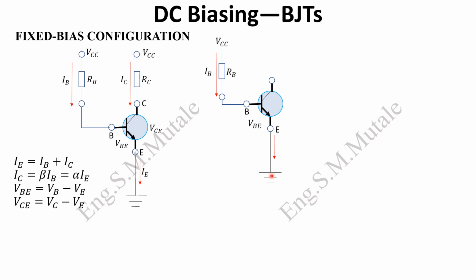So this voltage, as it comes from the point of excitation, you are going to have a voltage drop across the base. You're going to have a voltage drop here, which we are calling VBE, and then it goes to the ground. The one thing you need to note is that VBE is 0.7 for all transistors. They may or may not give you this, but whenever you see VBE, just know it's a constant of 0.7.